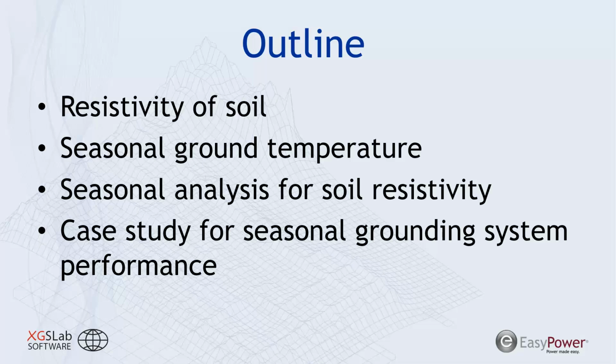So to get those goals accomplished, we're going to give everyone some background on soil resistivity and discuss the seasonal ground temperature variation that we see and how that relates to the seasonal variation in soil resistivity. And then we'll switch over to the XGSLab software and do a case study to evaluate a grounding system's seasonal performance.